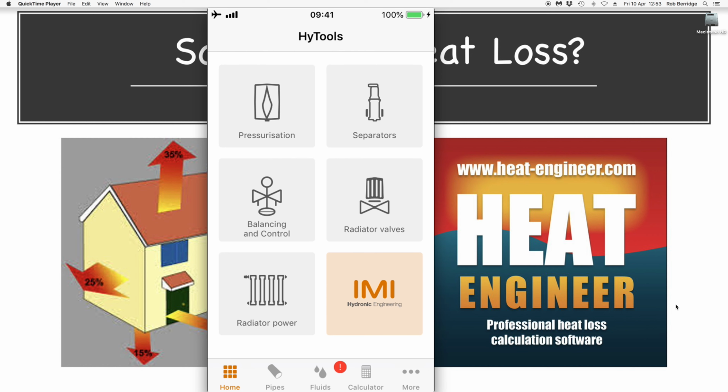Your average combination boiler generally works on about a 35-degree temperature rise. Now, I'm just going to do this. I'm not going to go right into detail about the calculation process and specific heat capacity of water, but if I put in a 30 kilowatt boiler, I'm just going to do the calculation as we speak. So it's 30 kilowatts divided by, inside parenthesis, 4.19, which is the specific heat capacity of water, and then times, as we said, a 35-degree temperature rise. Close your parenthesis, and equals.